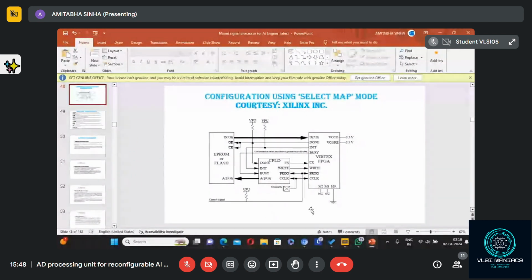Then the bare board, after getting it, you insert the components and solder them. For testing you can solder at the lab, but for bulk manufacturing, we do it using wave soldering machines. Some kind of die is prepared, and using those dies, automatically the chips are soldered.